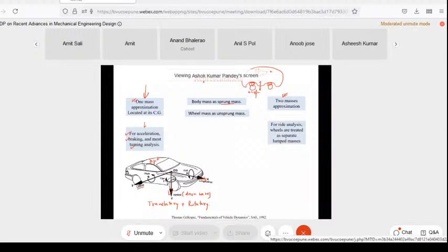So along the x-axis your vehicle rotates, we call it rolling of the vehicle. And when it does along the y-axis, like this one goes up, this one goes down, this is called pitching. And along this direction, this is called yaw angle, right? So these are 6 degrees of freedom: longitudinal, lateral, vertical, they are translatory motion. Then roll, pitch, and yaw, they are rotatory motion. And whenever we try to write down the equation of motion of the full car body, we need to find out all these situations: rolling, pitching, yawing, all 6 degrees of freedom.